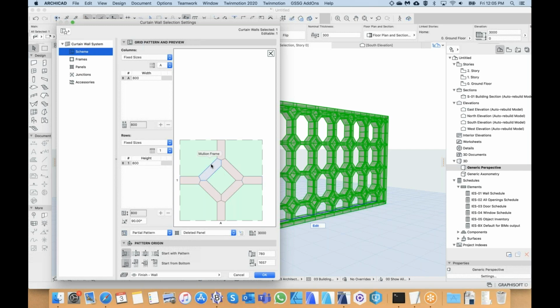I can't move these frames directly in here, but this is saved as one kind of custom scheme. But because it's a custom scheme, I can click on different components. For example, I can click the inner parts and set this to be the main panel, and click on the outer part and change this to a distinct panel. I can also choose the frames and change the frame type and sizes within the frames. So I've clicked on the outer part, set to distinct, selected the middle part, and set this to main panel.